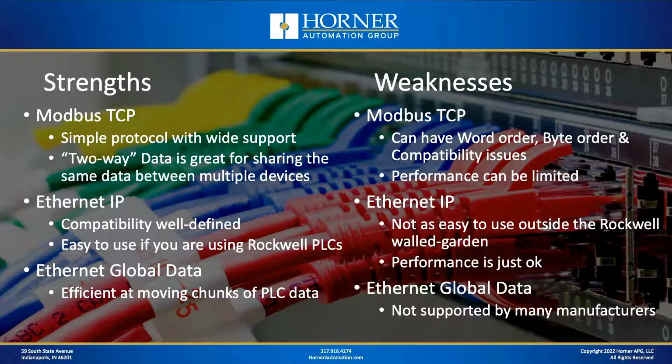Let's move on to Ethernet IP. Its compatibility is good because it's a well-defined protocol, and there are well-defined compatibility tests that are typically run on devices that talk on the network. So whereas Modbus TCP, that's a weakness, for Ethernet IP, that's a strength.